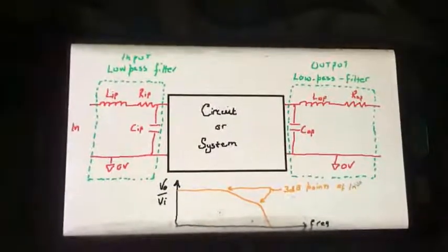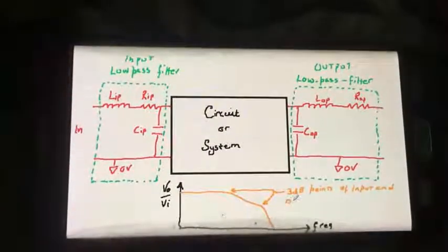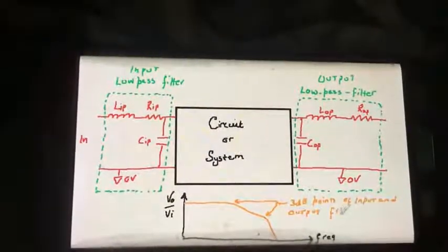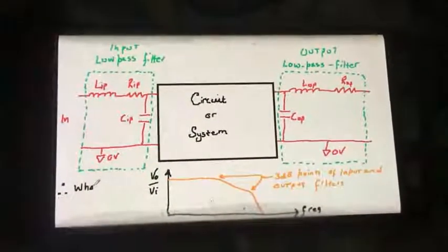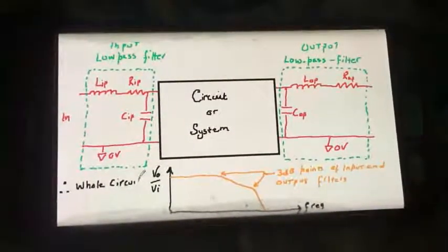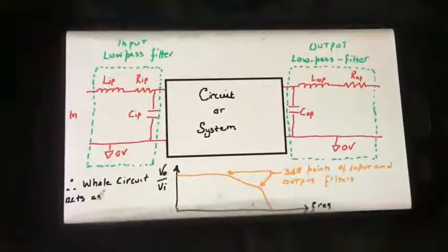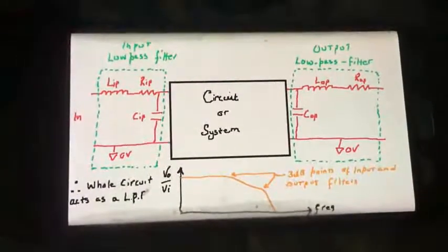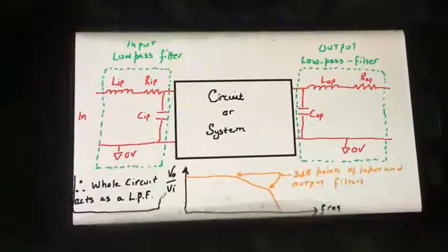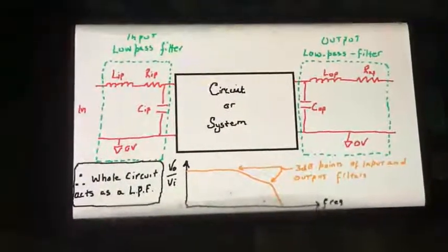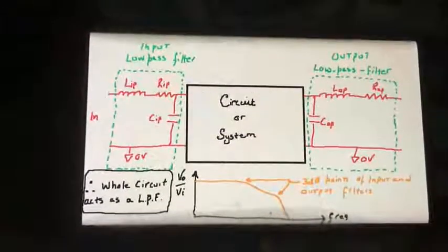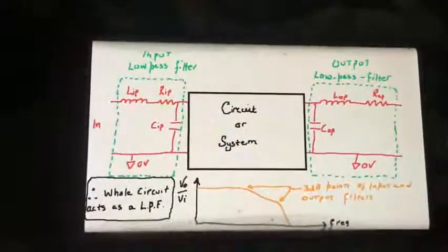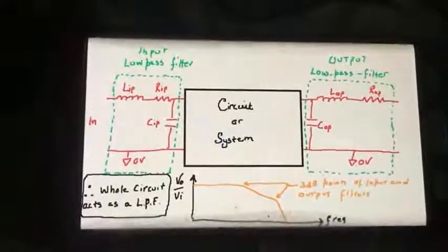You should also note that although we've just been discussing input and output wires, parasitics exist internally among all the wires within the block. And there are even very small resistances between wires because there's no such thing as a perfect insulator between them. Parasitics are one reason, but not the only reason, why designing circuits to operate at higher frequencies is a more challenging task than designing them to operate at lower ones.